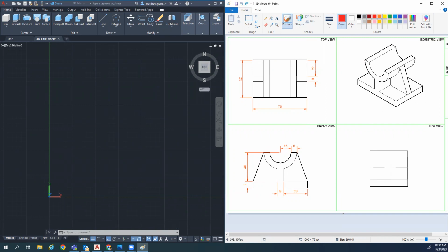We can draw basically this front Y-shaped thing, okay? And then we can rotate it so that it's going the correct orientation on the front plane here. And then we can extrude it back to get most of the drawing in one step. So that's what we're going to do instead of breaking it down into the base and whatnot. So we're going to learn a new tool today called 3D Rotate, also called the Rotate Gizmo. Learn how to work that. Okay. So here we go.